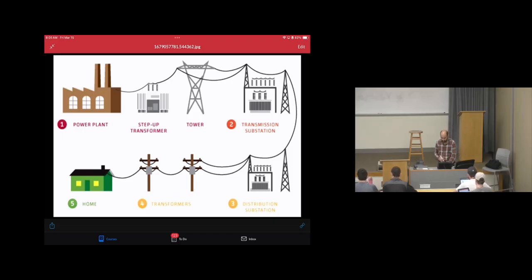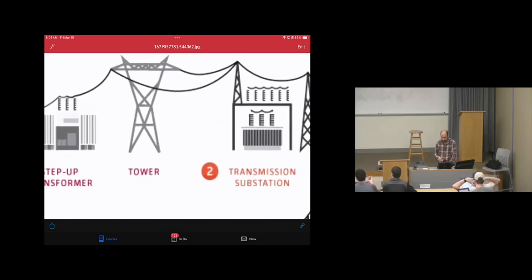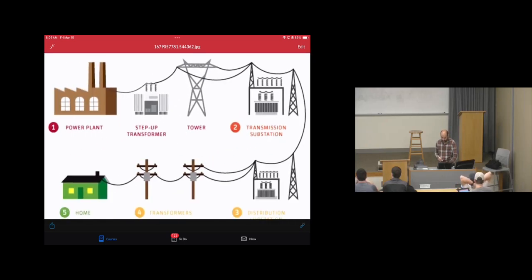The power is actually being transmitted using the towers, like this tower. Since there will be losses, we realized if we can make the voltage higher, the losses will be low, because the loss is I squared times Z. Z is constant because it's the tower itself, or the power lines. If we reduce I, then we can get lower losses. We know S equals V times I conjugate. For the same amount of S, increase V, what will happen to I?